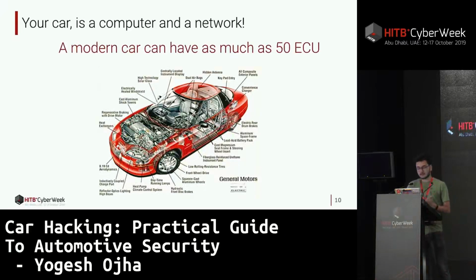So in layman's terms, what really happens in CAN bus is that the messages are sent on a bus, and the CAN network never determines who is the receiver. What is happening is all of these receivers receive the message and find out whether that is intended for them or not. They have something called an arbitration ID, the receiver's ID, and then they find out whether that particular message is for me or not. That's how generally it works.